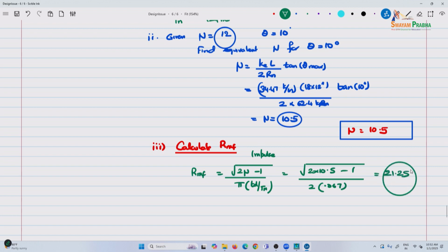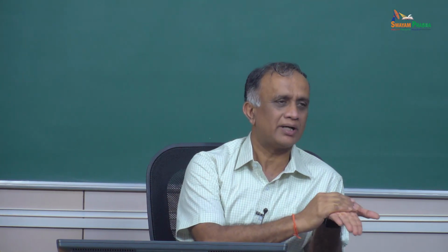Now, this is why I say do not equate it to seismic RMFs. Here RMF is anything we calculate, the response modification factor. I think they should have called it something else, or we can call it something else. Because in seismic, you're limited, those are all fixed quantities based on the level of ductility that is desired. If you are low ductile like masonry, then you may have an RMF of 1.5 to 2.